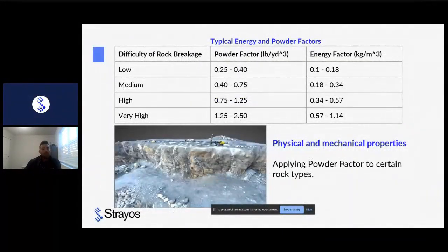So when we tailor this to blasting, depending on the quality of your rock, if you've never blasted in this pit or this site before, you want to look at what powder factor you might be applying. And this can go several different ways, depending on your blast design. If you have a desired hole size or pattern that you're trying to accomplish, or if you're regulated in any way by pounds per delay, understanding the powder factor, pounds per cubic yard, or kilograms per cubic meter, depends on how you're going to be shooting this rock and what level of explosives you're applying to it.